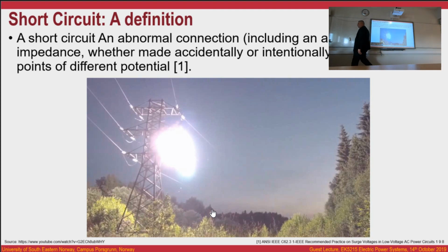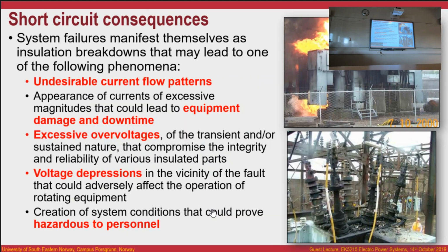Something that you must understand, for short circuits, you require low impedance. Something that is closing a circuit with a very low impedance. Second, you need a potential difference. Phase A, phase B. Short circuit, okay? Are you with me? What are the consequences of a short circuit?